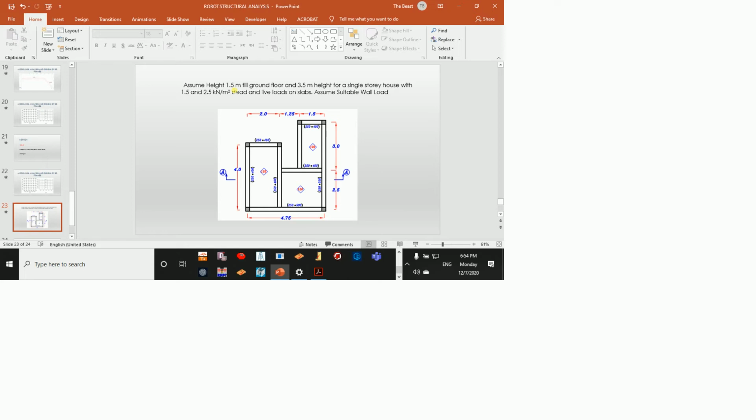So you need to know the difference between the level of the sunken slab and the finishing level of the other slabs that needs to be filled with the material. For example, if it's soil, then 18 is normally the unit weight, multiplied by the height of the fill. That differs depending on the height of the sunken slab.